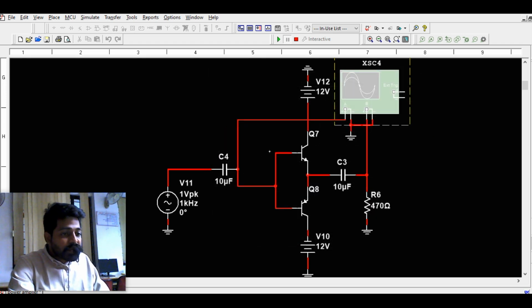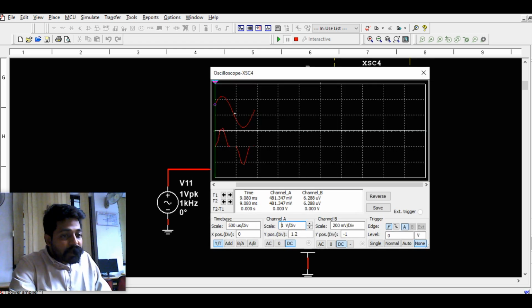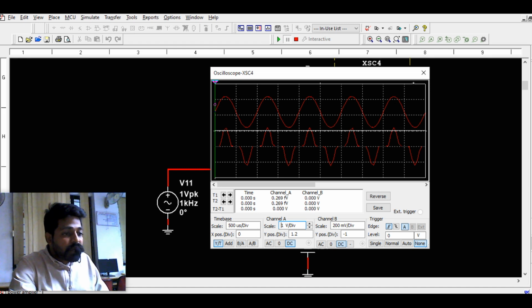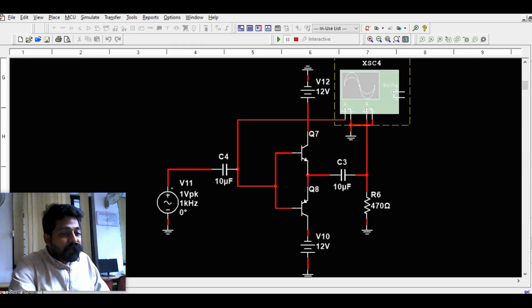That is because the transistor needs 0.7 volts to come out of the cutoff. So this transistor also needs minus 0.7, right? So 0.7 here and 0.7 here will be taken by the two transistors to come out of the cutoff. The remaining voltage of the positive peak and negative peak will appear across the DC line, so crossing the DC line you can see the distortion. So the distorted waveform, the crossover distortion, we can see at the output in the class B power amplifier when we give a very weak signal. That is one observation we have to make finally.